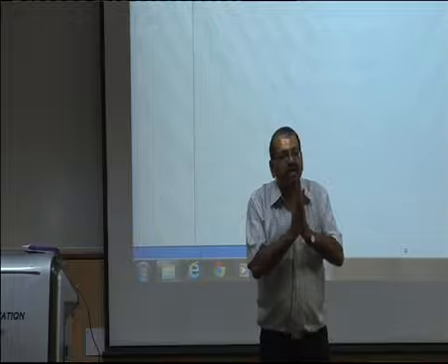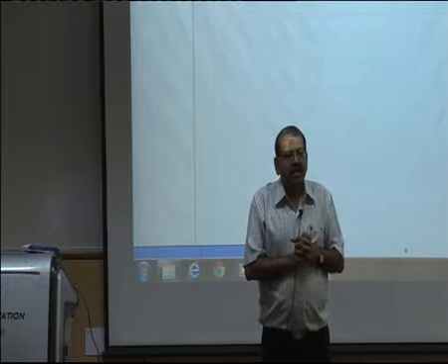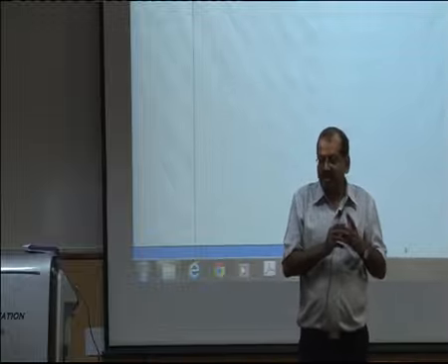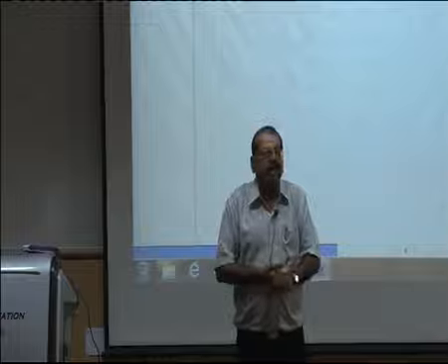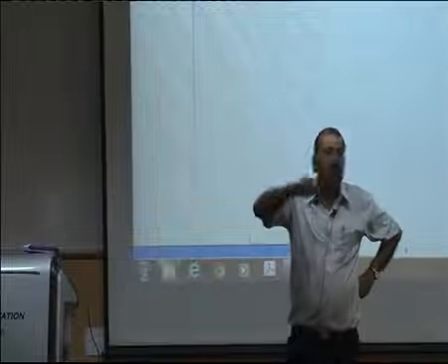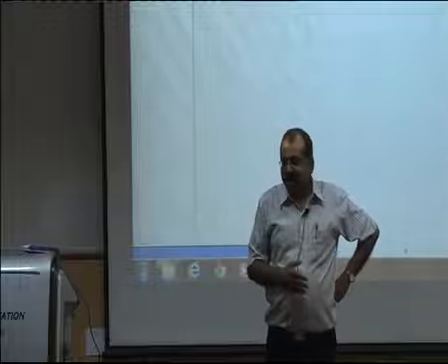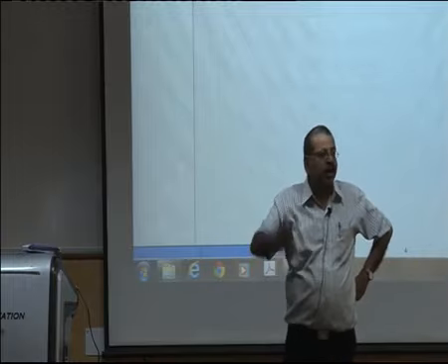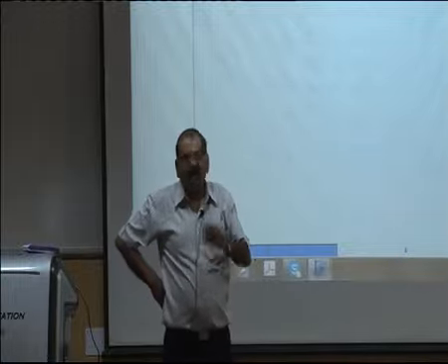And how do I write the relation between the old axes and new axes when I rotate the axes? I write them in terms of which quantity? There is something called direction cosines. When we rotate axes, we always write these relations between old and new axes in terms of direction cosines. What is a direction cosine? The cosine of the angle between the new x prime and the old x is the direction cosine for the x axis. Similarly, the direction cosine of the y axis will be the cosine of the angle between the new y axis and the old y axis, and so on.